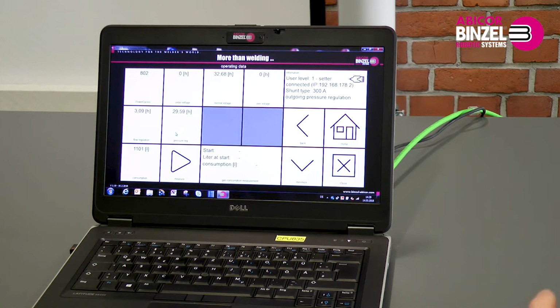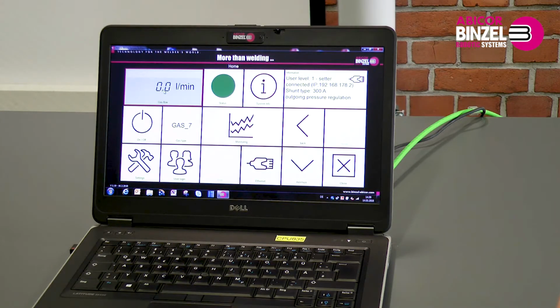You can use the service software to do a long-term measurement without having a connection between the service software and the EWR2 at all times. To perform this function, click on Measurement. As a result, a data packet is stored at the present time and present date with the current EWR2 with serial number on the computer showing the total amount of gas measured. If after any period of time you connect the same computer to the EWR2 and then click on Measurement again, you will see how much gas has flowed through the EWR2 from the start of the measurement period.